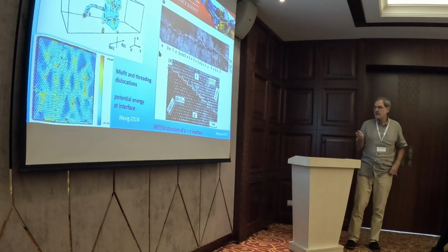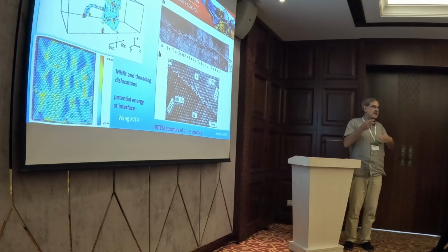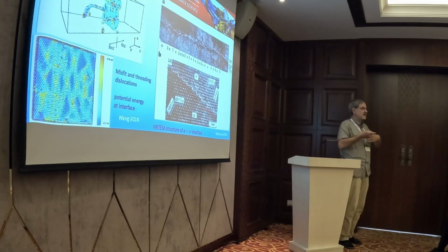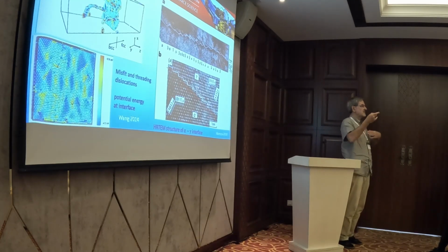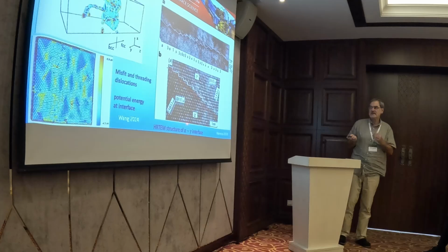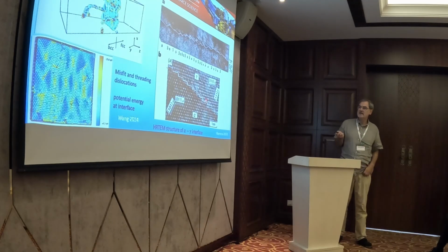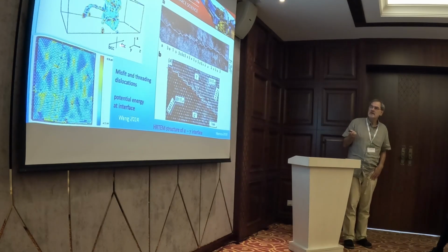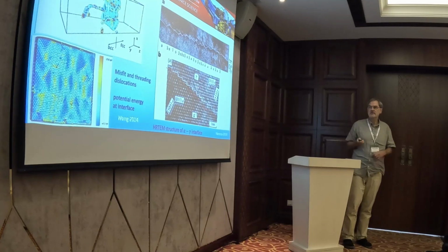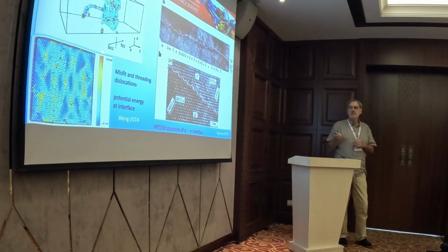So what can you do? You can, for instance, study the interface. Now, I do not show dynamics here. It's just the interface between the BCC phase and the FCC phase. And on the right-hand side, you see some high-resolution TEM measurements of how such an interface looks. And this would be what one can see in the simulation data, a very complex interface.